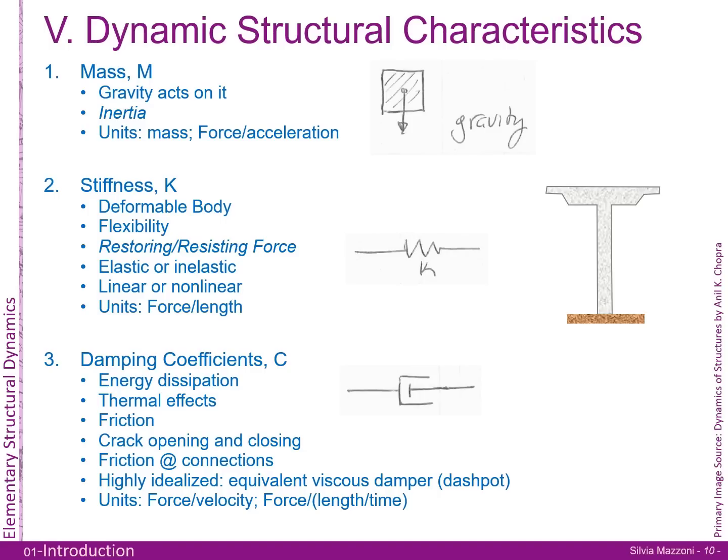Thermal effects can be accounted for with damping. Friction. In reinforced concrete, it represents crack opening and closing. In steel structures, the friction at the connections, maybe your bolted connections that actually slide through and dissipate energy. If we design it carefully, that can actually be a good thing.